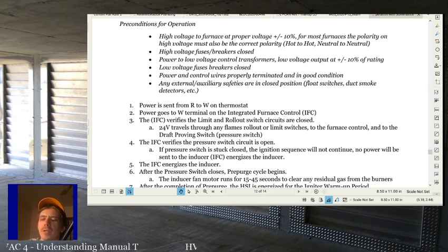If you've got some kind of issues with your wires, it's going to cause some problem that you may not be able to immediately figure out. So it's always good to double check. Does everything actually look like it's terminated properly? Are your connections tight? Is it in good condition? Are your wires causing the problem, or is the problem with the equipment itself?